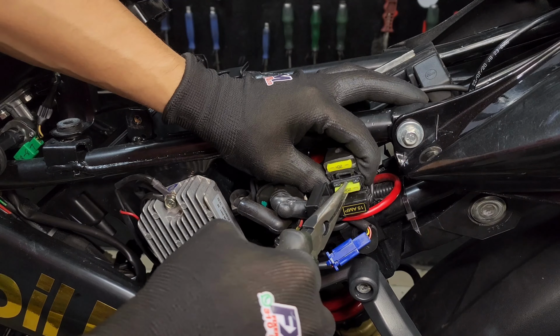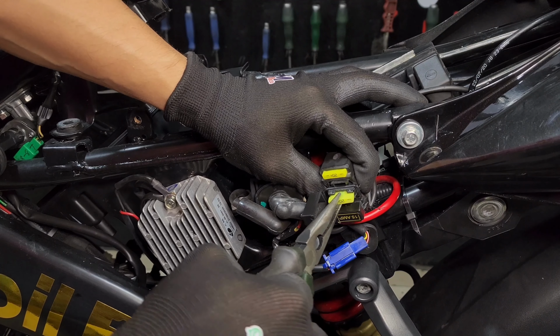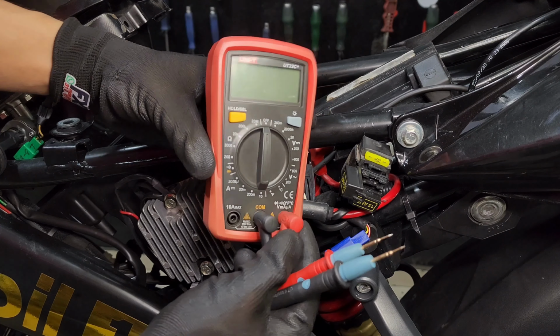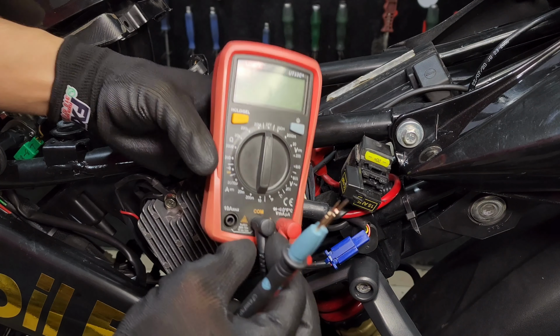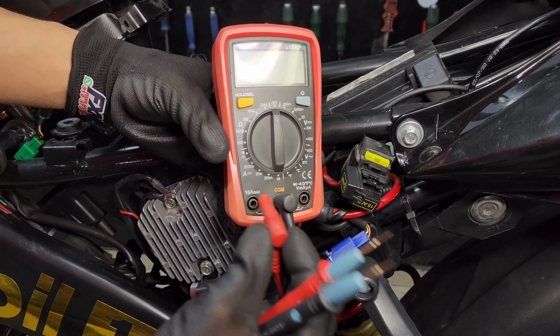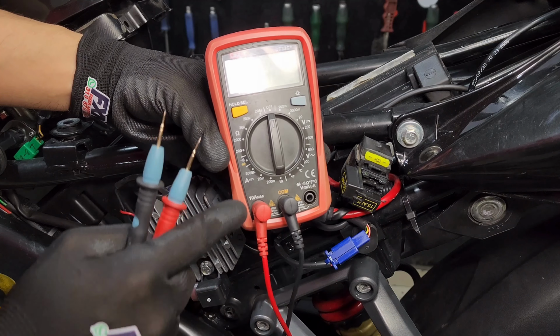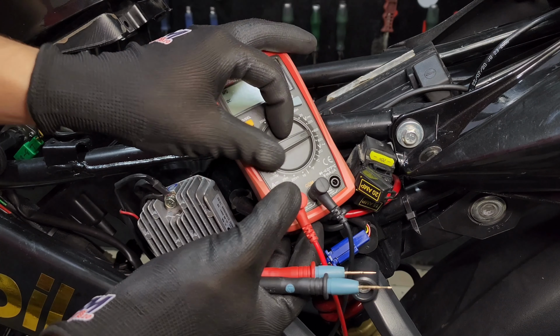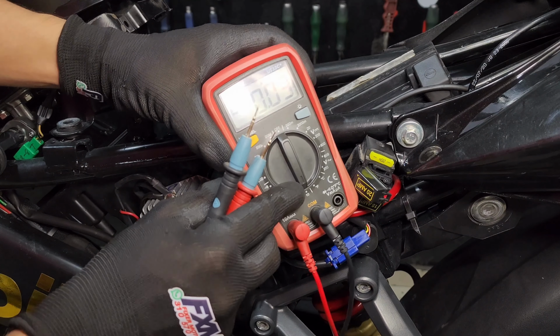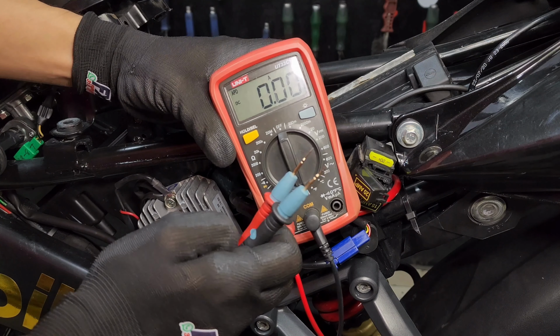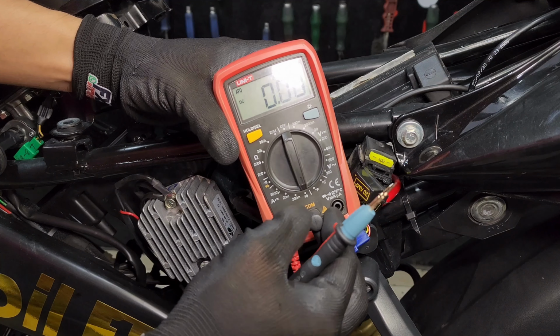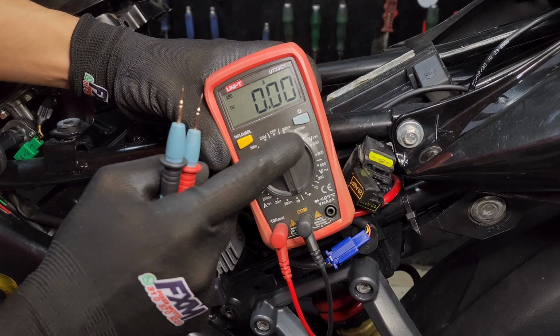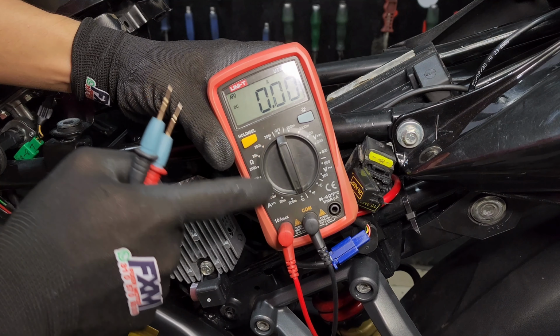So we remove the main fuse, the 20 amp one, and with the multimeter, we are going to make that series circuit. For that, it is important to change the place of the tips, because here the maximum scale measured is 10 amps, which is the multimeter's maximum. But to make this measurement, ironically, I can't do it with this multimeter because at some point it measures wrong.